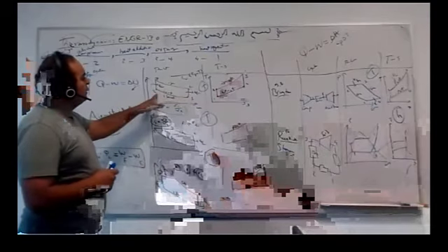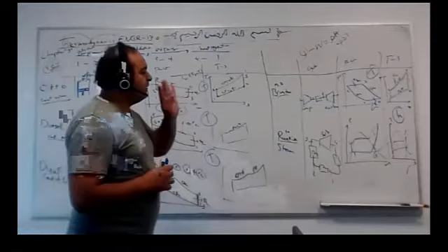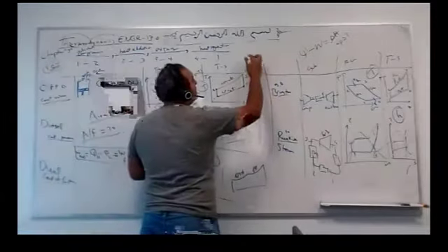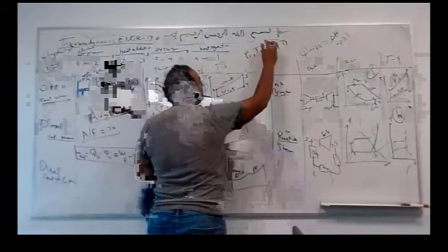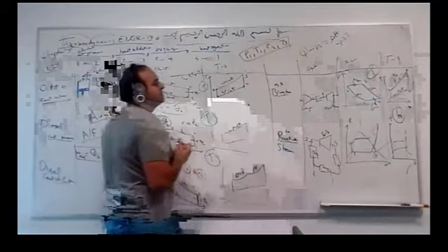For all of these cycles, except Dual, you need to have 4 pieces of information. For example, P1, T1, let's say V2, and T3. That's it. You have 4 pieces of information. For Otto, Diesel, Dual, but plus 1. Brayton, Rankine: if you have 4 pieces of information, let's say P1, T1, V2, T3, or anything, any 4 pieces of information like this, you can get everything in a cycle, from 4 values: state 1, and 1 piece of information at state 2, 1 at state 3.